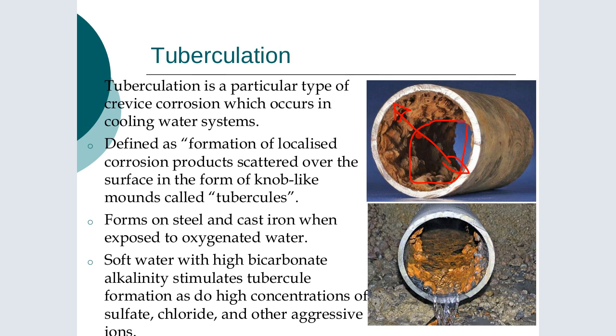And if you decrease this diameter substantially, you have quite a heavy influence on the flow rate. So if we take it that the flow rate is constant, the pressure drop is proportional, if I can write it here, to 1/d to the power of 4. Okay, so it is extremely sensitive to it.